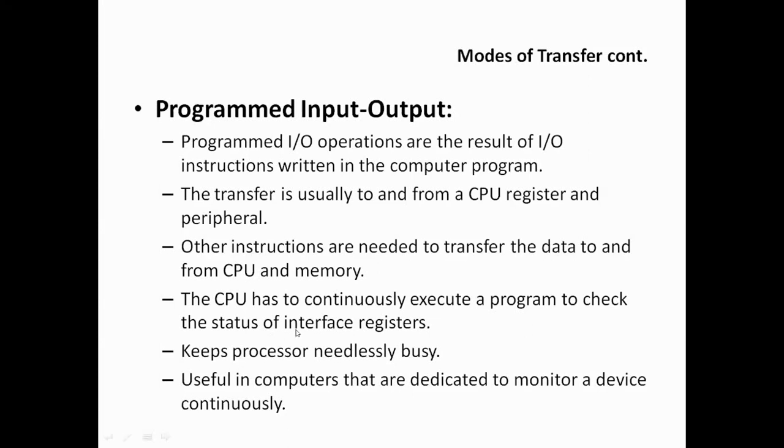This method is obviously problematic in the sense that it keeps the processor needlessly busy, because if you have to transfer data, the time taken for data transfer is fine, but the time to continuously run that program, maybe it may take many milliseconds, many nanoseconds.